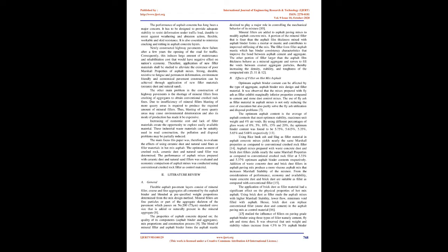The utilization of waste material as filler in asphalt concrete mixes gives a significant solution to disposal problems and saves the environment. Use of waste materials makes for economical and environmentally safe pavement [5, 6, 7]. The performance of asphalt concrete has long been a major concern. It has to be designed to provide adequate stability to resist deformation under traffic load, be durable to resist weathering and abrasion action, and be flexible, workable, and skid resistant. It is also essential to minimize cracking and rutting in asphalt concrete layers.